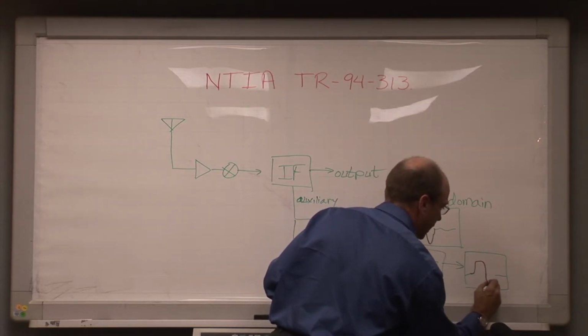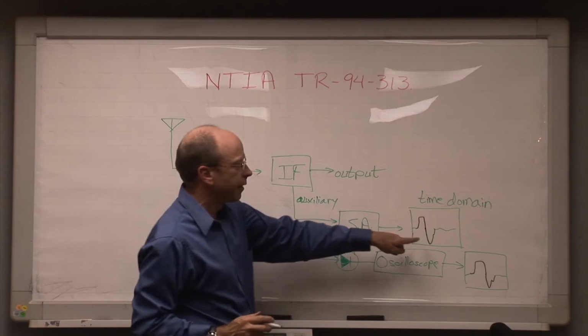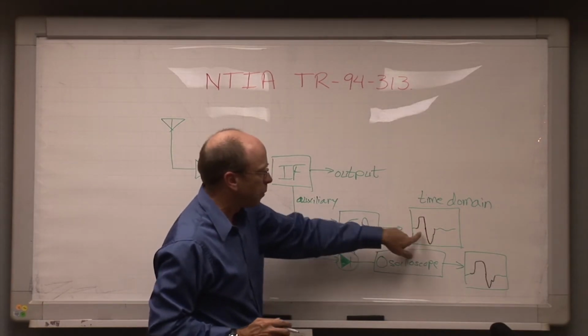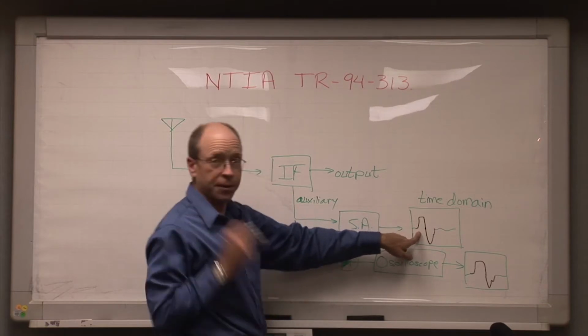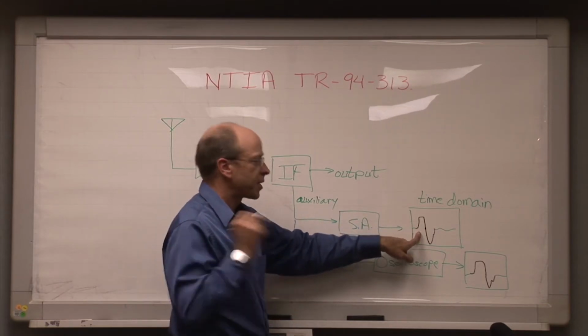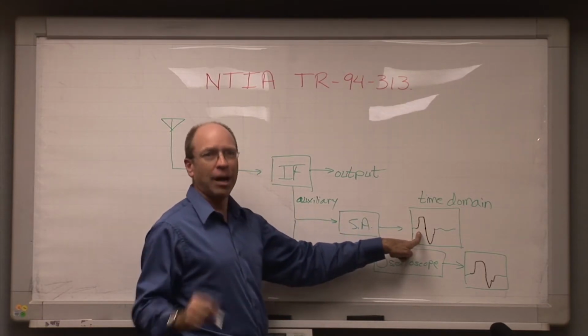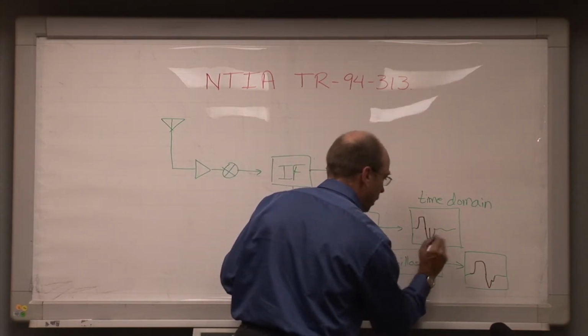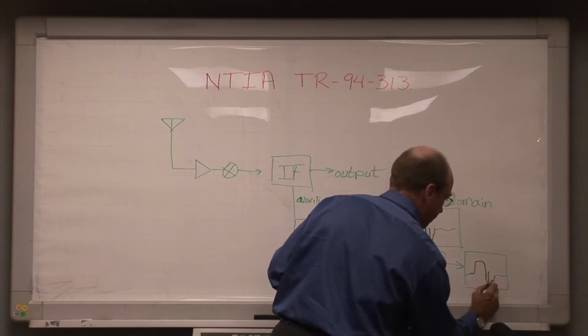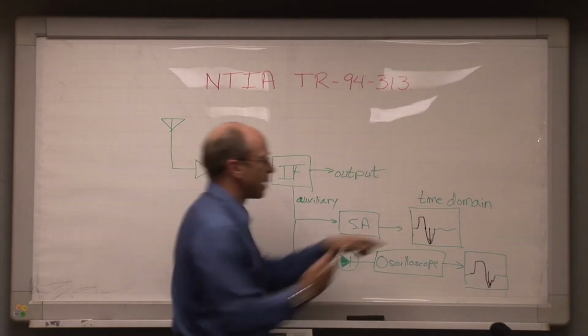We're going to see the apparent level of the desired signal drop below the level that we know the receiver's getting it at. Now what's happening is the desired signal's not dropping down. The response of the front-end amplifier is dropping down, and the result is that we see this dip occur as a result of the amplifier having been hit by this high-power pulse,